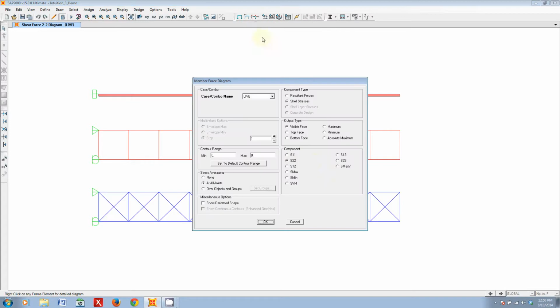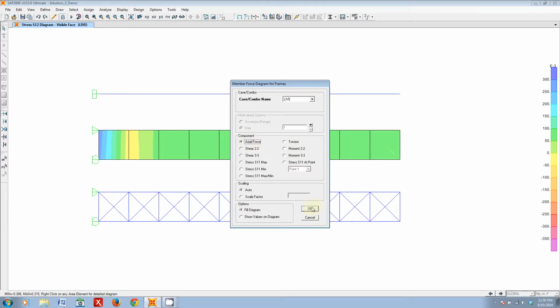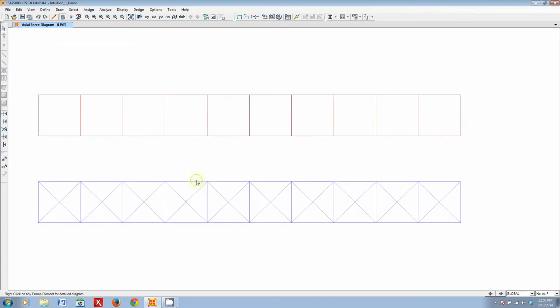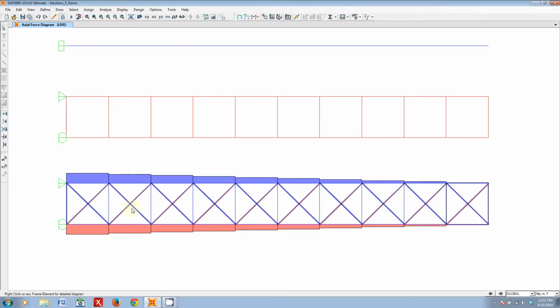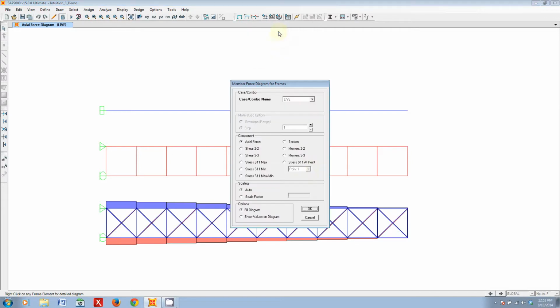And if we look at that in the shell model, that means that basically our shear is constant throughout the beam, more or less. Now let's check out, that would have to mean that pretty much all of our tendons carry pretty much the same force, and indeed that is the case. And because it doesn't change sign, our tensile cords are always pointing down, and our compressive cords are always going up throughout the whole thing, and it's constant. So cool, that's correct. Oh, this is working out better than I'd hoped.